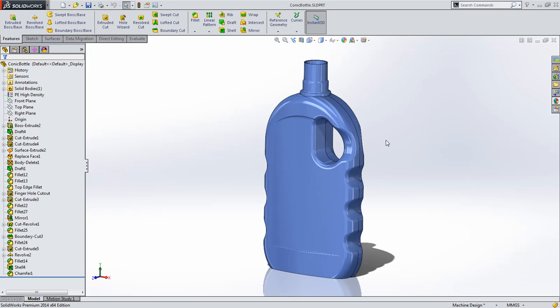In consumer product design and other applications where aesthetics are important, constant and variable radius fillets have limited use due to the sharp change in curvature. Curvature continuous fillets produce smooth results but are limited to a single constant radius. Now the fillet feature in SOLIDWORKS 2014 gives you even more control to define a new type of shape, a constant or variable radius conic fillet.